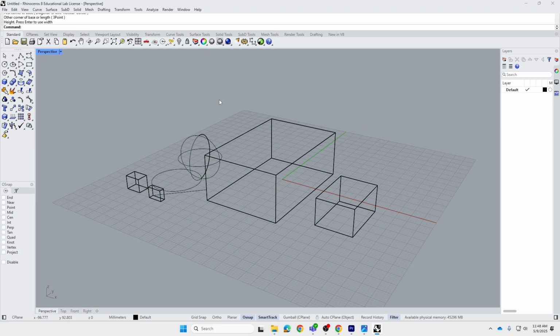Now before we move on, you should turn on 2 different settings. The first is to enable OSNAP. So in this corner of the screen, you can see a list of different snapping options. Let's turn them on. And then what you'll notice is when you create objects, let's say this line here, the position that they're created may snap on to different parts of the project.